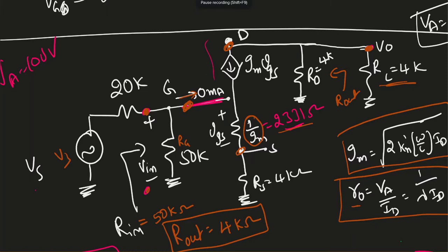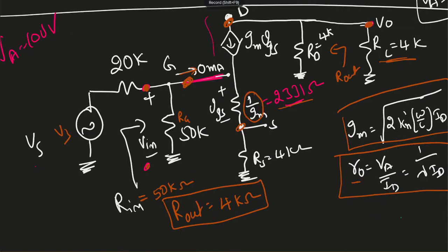Based on that resistance, you may want to vary the load resistance. If you look at the Thevenin theorem, remember, if the internal resistance is equal to the load resistance, you will transfer the maximum power. So if that is the condition, you can have the load resistance equal to the output resistance to get the maximum power. Now our goal is finding the gain. Gain is nothing but output voltage over input voltage. This is AV with load.